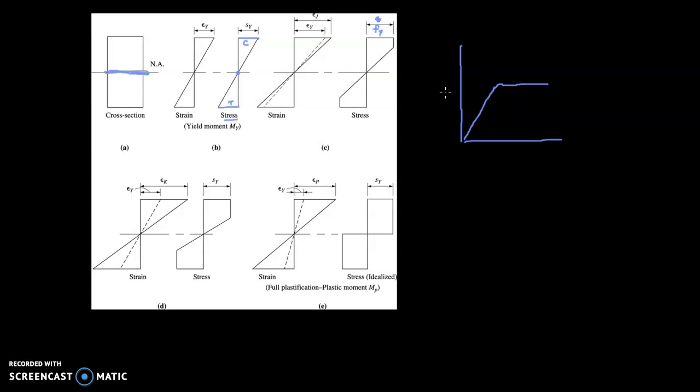So this is the amount of stress, which we use as sigma, or we could use F now. We're talking about bending in beams. And down here we see strain. So you generally, when designing a structure, don't want the material to exceed the yield stress, because what happens is you get this massive elongation with little to no additional stress.